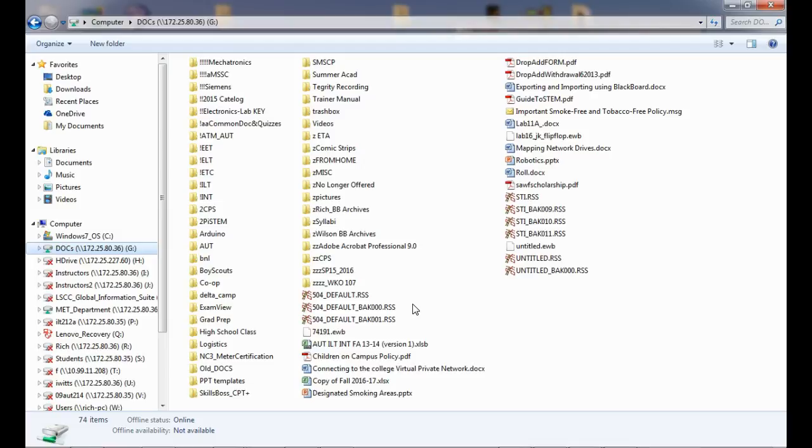And then our department, we have our own route. So we're 175.25.80, and they leave that to us, so we can assign those IPs the way we want to. So if we could hook this thing up to the college's network, then I could access these PLCs from my house, right? So right now we can't, because these IPs right here won't be routed. All that makes sense now?